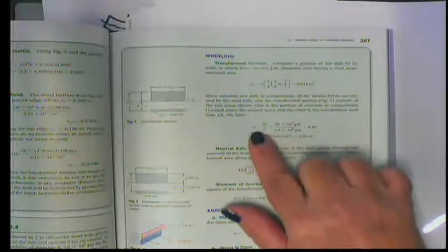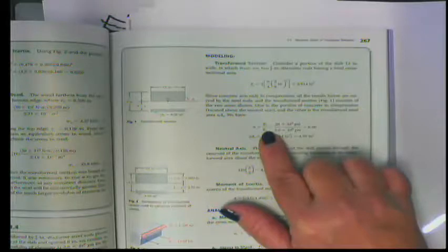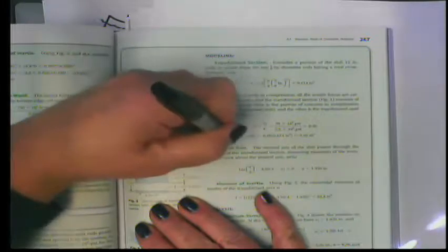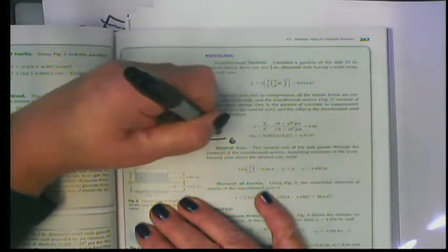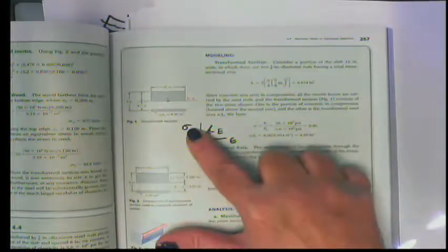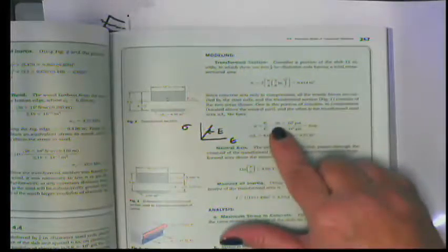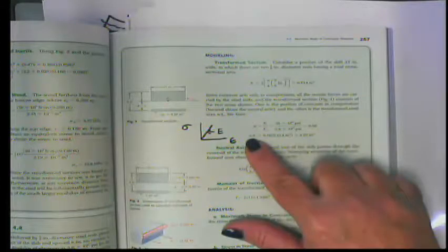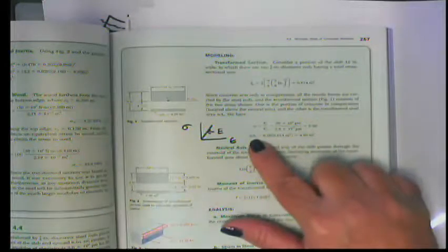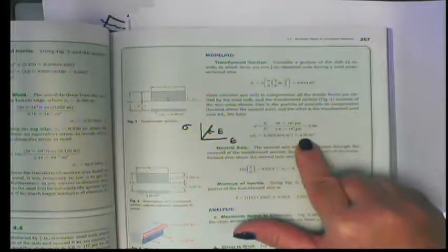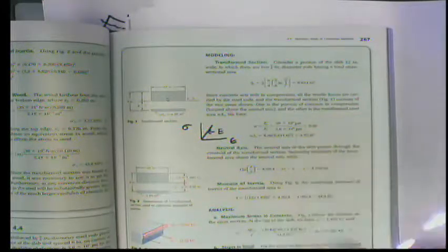Then you calculate the ratio of the moduli of elasticity, which, as you recall, the modulus of elasticity for any material is the slope of this line, or in other words, it's how stretchy it is, how much it expands, how much epsilon there is for a given unit of sigma. And so we put that ratio, and this one is 8.06. So then you multiply that ratio of the moduli of elasticity by the actual area of the rebar in that slab width, and you get a transformed area of 4.95 inches squared.